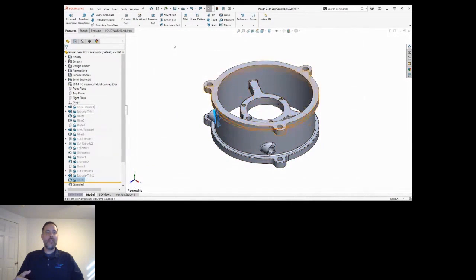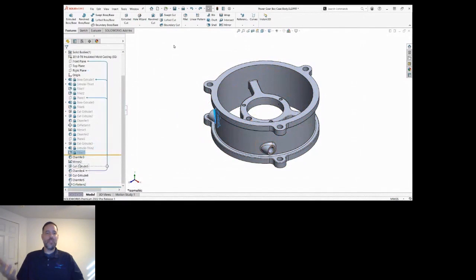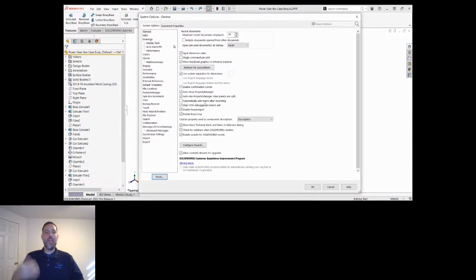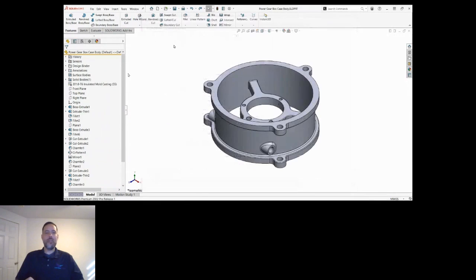And then anything above where you drag it to, it's locked. So you make changes below it, it won't rebuild. That goes back to that rebuild time, right? And then you can say, okay, I don't want it to go through and check all this stuff every time I make a change. And that way you can do all your design. Once you drag it back up to the top, it will rebuild everything though.